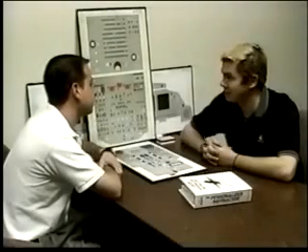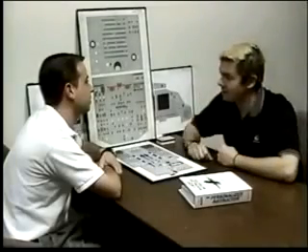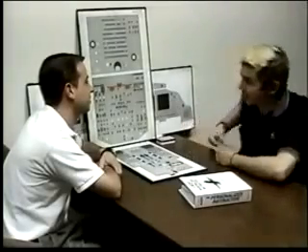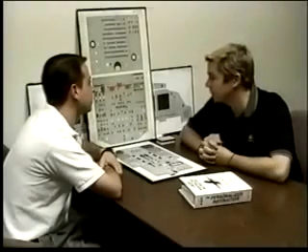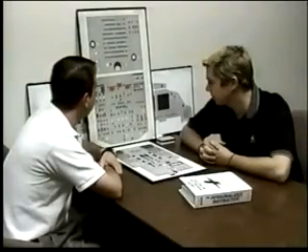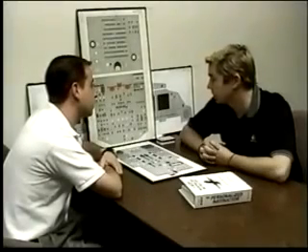Ditching switch. What occurs when you select the ditching switch to on? As crazy as it sounds, my instructor told me this, and I have never forgotten it. There are valves that close. There's the avionics inlet and extract, the 2 pack valves, the ram air valve, and the outflow valve. The outflow valve only works if the pressurization system's in auto. Can you think of a time in normal operations that you might use the ditching switch? During de-icing.